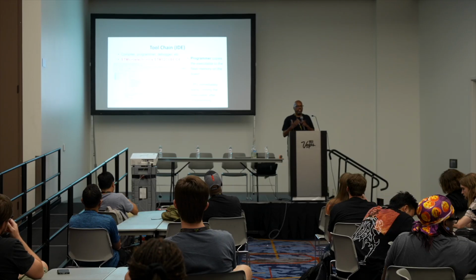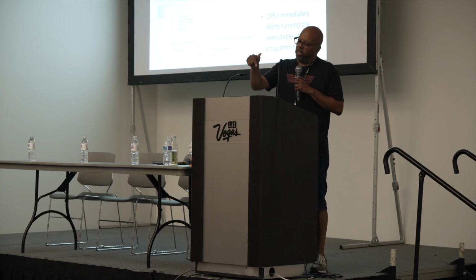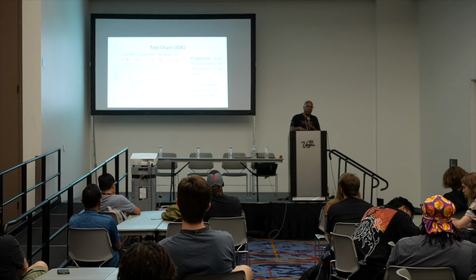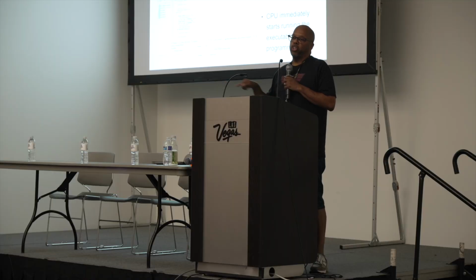So the one difference in an embedded system IDE is that you have a programmer that's attached to it. One thing you have to do is, once you compile the code, you actually cross-compile the code. Normally if I compile code on this machine, it'll be compiled to execute on this machine, on this microprocessor. But with an embedded system, you compile it on this machine to run on a different processor. That's called a cross-compiler.